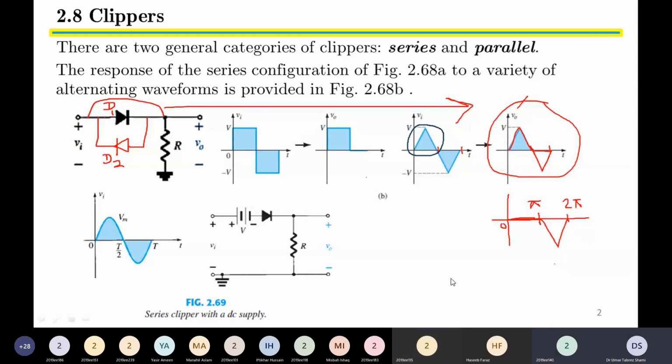Well, I don't really understand your question, but just the diode with a 0.7 power supply is not enough. We will have to also take care of the direction of current being allowed to flow. Therefore, the 0.7 volt power supply, which represents the barrier potential of the diode, along with the ideal direction of the diode, will now be required. Only when these two conditions are fulfilled can you apply source transformation and get the result that you are looking for.